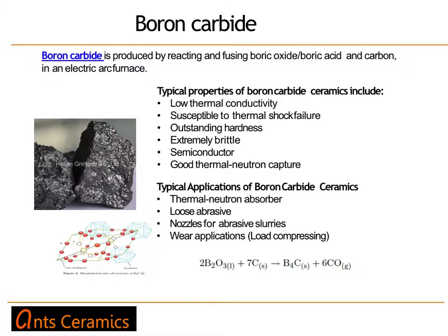Another important advanced ceramic component is boron carbide. Boron carbide has a huge application in thermal neutron absorbers. It is used as a very good loose abrasive because of its extreme and outstanding hardness. And then these are also being used as armor plates. So boron carbide is produced by reacting and fusion of boric oxide or boric acid and carbon in an electric arc furnace.